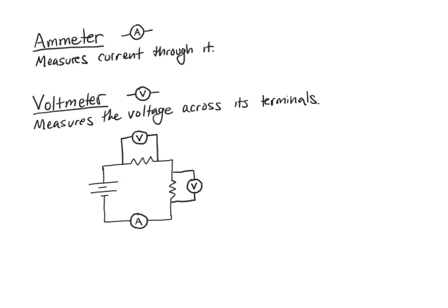Now there are two ways to approach this. One thing I could do is add these two voltages together and I should arrive at the voltage of my battery. The other thing I can do is place a third voltmeter across the ends of my battery. This also places a limitation on the properties of the ammeter. I still want to make sure that adding the ammeter and voltmeter to my circuit hasn't changed my circuit in any material way. Just like we talked about with the voltmeters, we want to make sure that no current goes through them, otherwise it would ruin the consistency of the current through our resistors.